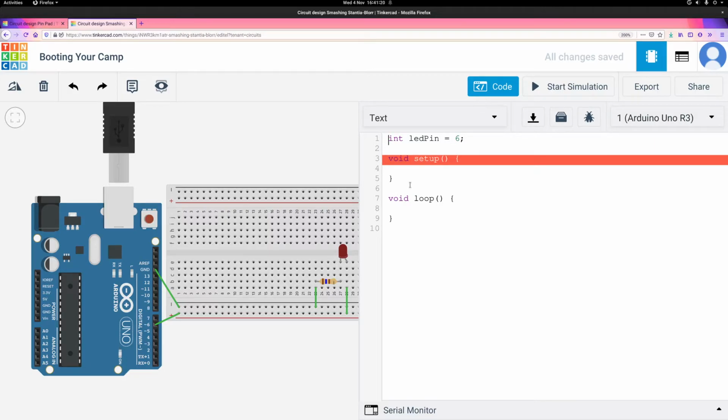Wonderful. Yes, and then the last thing that would be good to add on to this, and this is just a good practice thing, your code will work both ways, but we probably won't be changing this LED pin in the code because it's a physical property of the circuit. So what you can do is add const in front of it. That means that it's a constant.